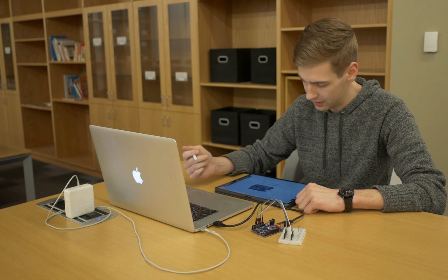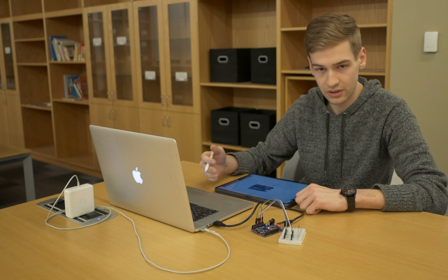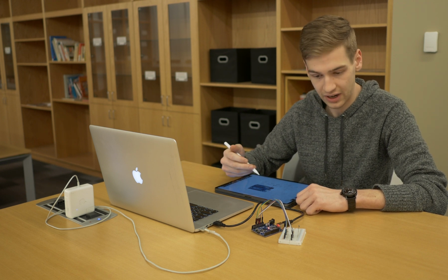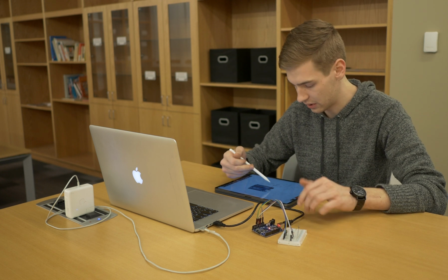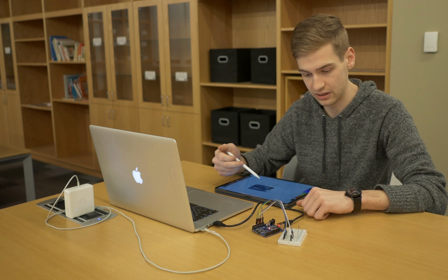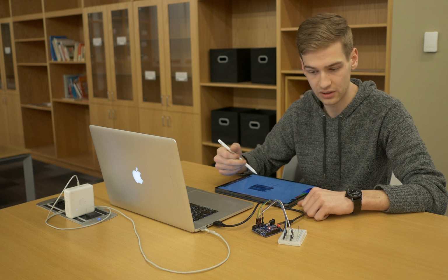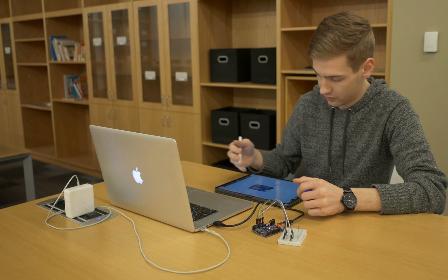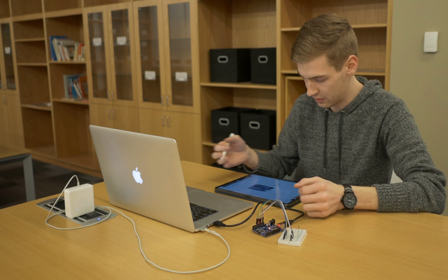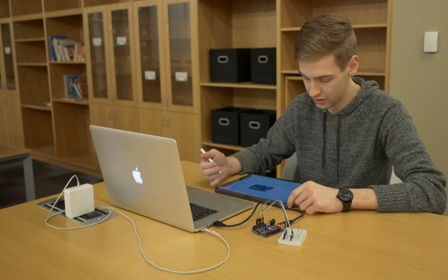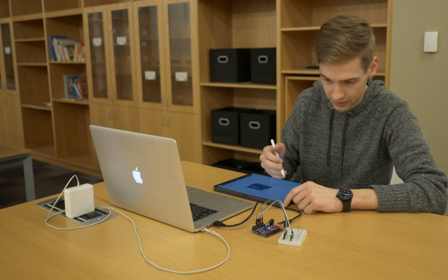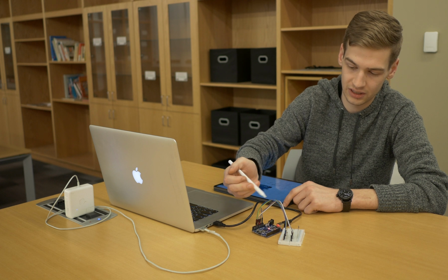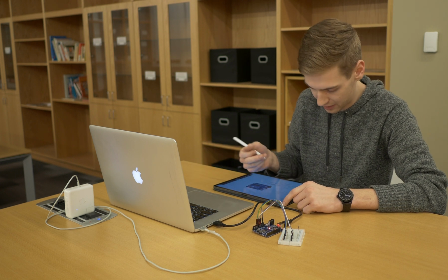So for our hardware, it was pretty simple. We were able to use an Arduino and use a voltage divider on a breadboard to read the voltage and the resistance into the analog pins in the Arduino. We started with a reference document here that was provided by Schumann, and I will try to color it so that it's got the same coloring as the ribbon cable up here.